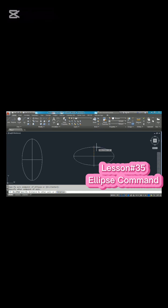That is, if the axis length is 10 units, we have to give 5 only, because it is already measuring from the center to the end of the other axis. So I am giving 5 units and pressing enter. Now you can see an ellipse has been drawn.